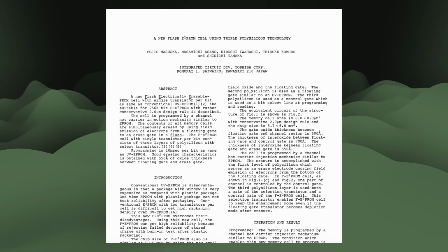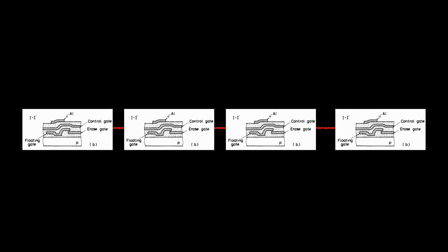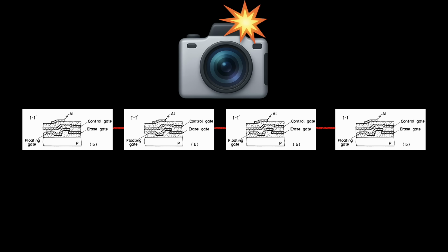So the erase gate and oxide are like a dedicated exit drain for the electrons, letting us string them together like DRAM does and erase them all at once. This reminded someone of the flash of a camera, ergo the name.